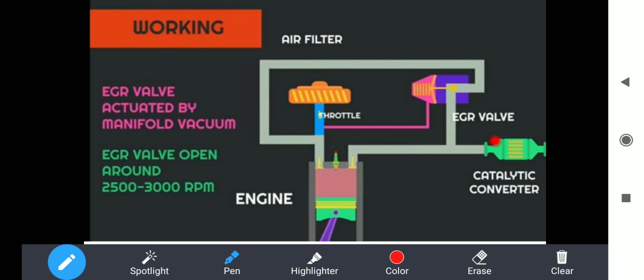Now there are electromechanical units for controlling this. The exhaust gas enters an EGR valve. From this EGR valve the pressure is controlled, or the valve opens at high engine speed, by which it releases the high pressure gases from the exhaust. Obviously the engine is moving at a faster rate, so the movement of the valves will also be at a faster rate.